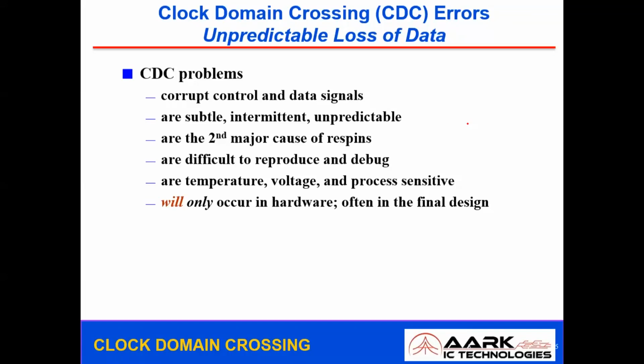And the most important aspect is the respins. Respin, in the sense, when you go through the 4 to 5 steps in a complete design flow, and after routing, if you identify there is an issue in the clock domain, and after STA, STA is not going to detect the asynchronous behaviors, so we'll create all of them as false paths. So when you detect it at a later stage, before you go to the tape out, coming back to the design, modifying your design, verifying it again and passing through all these steps again, we call it a respin.